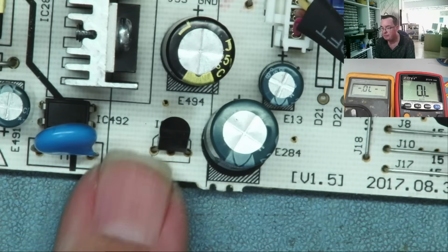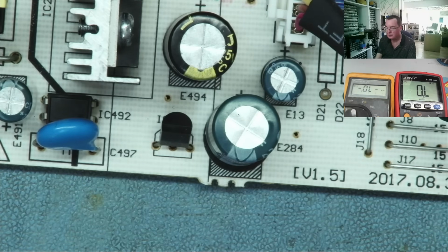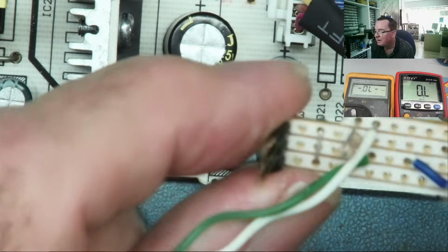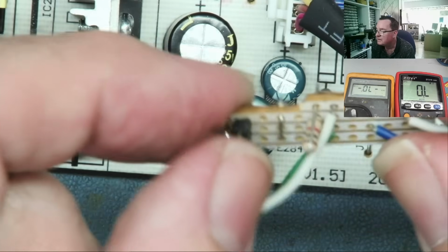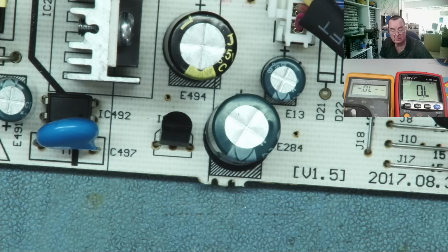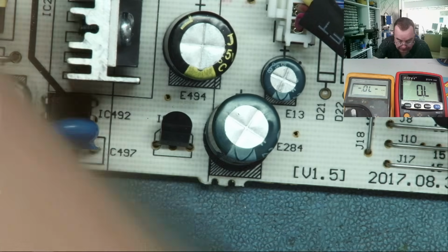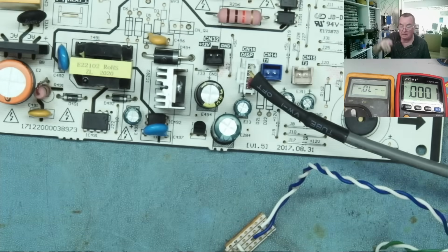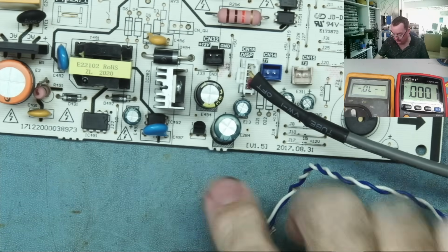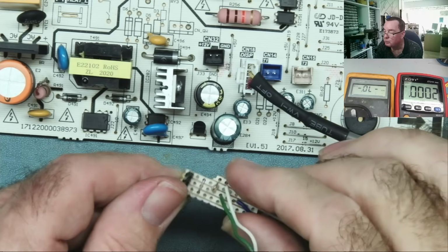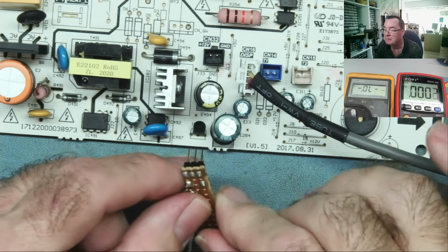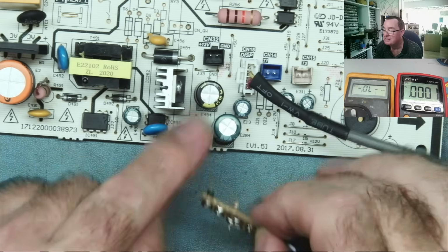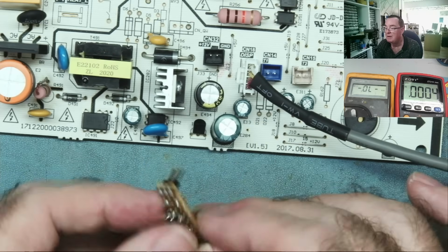One more thing on here I can easily test, and that is the TL431. And this is my in-circuit or out-of-circuit TL431 tester, okay? So this one, I put the meter onto volts. I connect my little tester. This is very simple to make, guys. One resistor and just a few pins. I will put the link in the video description. And you can connect it to the TL431 either way round.